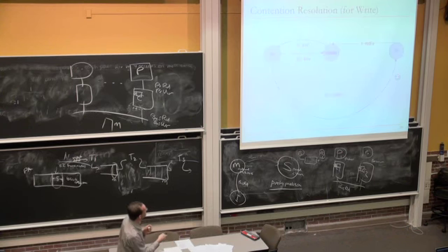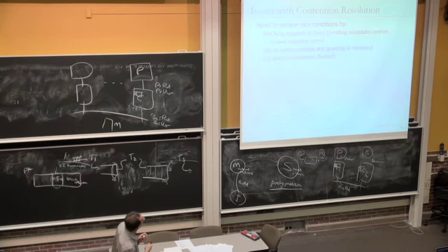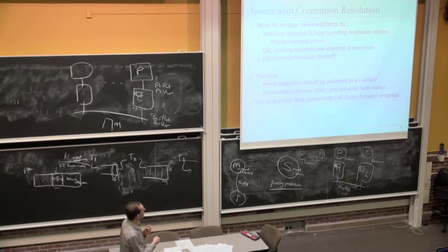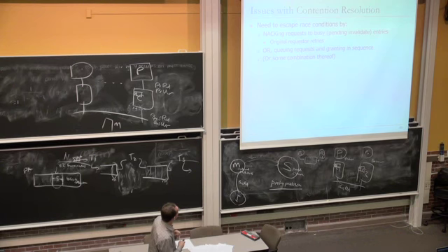But you could see that this kind of protocol can actually lead to some fairness issues, right? When two processors request the block, then who do you actually grant it to? Well, actually, which requester should be preferred in a conflict, right? And I will not go into this, but there could be ways of handling it. Basically, who do you send back the request to?